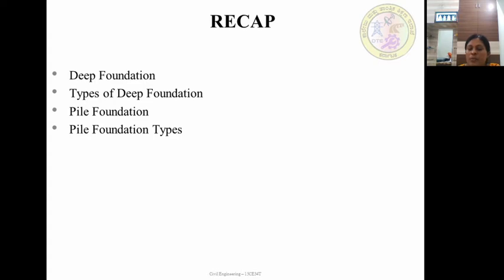These piles are used to confine the soil to increase the bearing capacity of the soil. They are used to isolate foundations from adjacent soil. Sheet piles are provided for retaining walls in beaches, and they are made of steel, driven into the ground to prevent the backfill from entering the excavation portion.